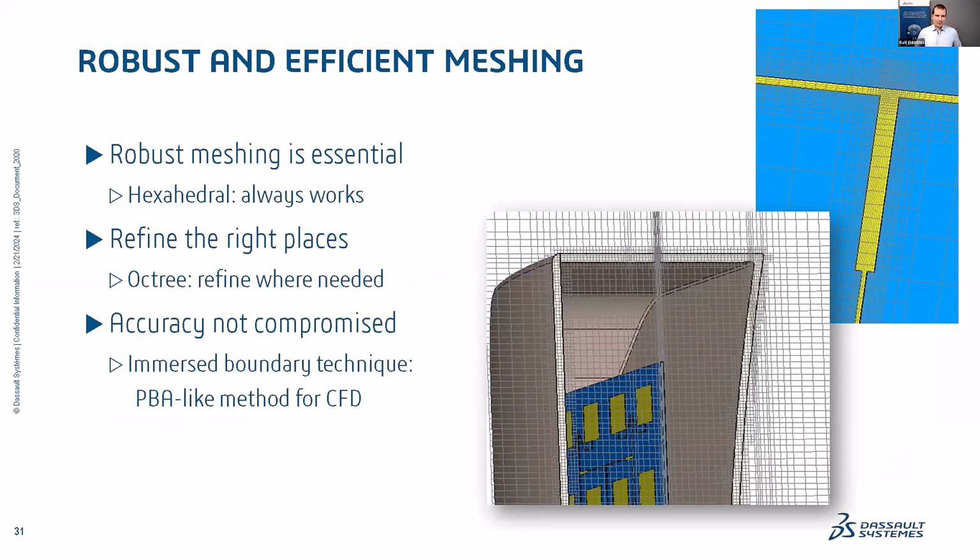So how do we go about the simulation? Well, first, it probably makes sense to take a look at how high the temperature will actually go if we simply put the antenna into a closed system. In this case, we'll be using the CHT solver again, so conjugate heat transfer solver, and we need to take some care with the meshing, make sure that the traces are resolved in those areas of high power loss as well.